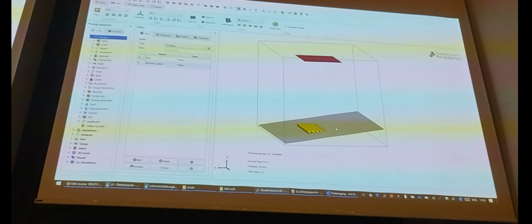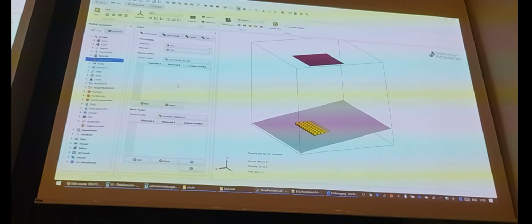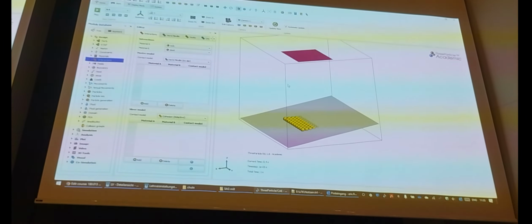No collisions defined yet. Right. We said we need a Hertz-Mindlin contact model or something similar, so that the particles know that they actually contact each other. So we go to interactions. Oh, yes, there is something missing. Rock has no interaction, and rock-steel has also no interaction. Nothing defined here.